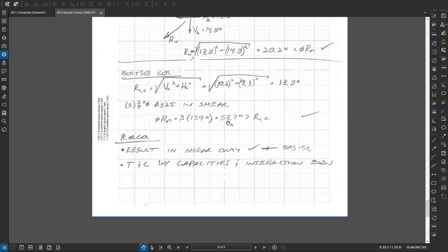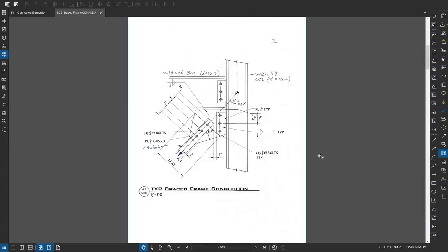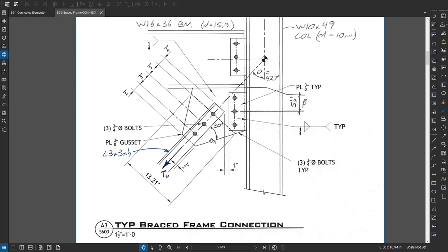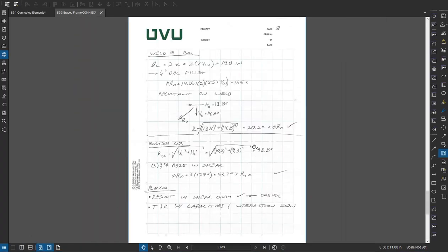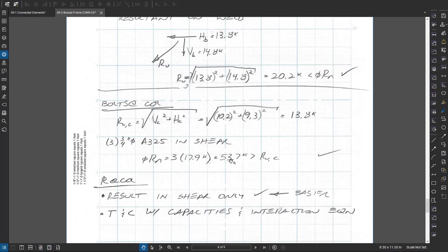What I'm seeing here based on the calcs is that if I wanted to back this off, I could probably go to a 1/4 inch plate, and 2 bolts here, and if this shortened vertically, this would pull in here. However, I would rather err on the side of a little stronger in connections, mainly because I'm not interested in a connection failing. I would rather have the member fail. So that's the size of the bolts. You can see it's quite a bit bigger.